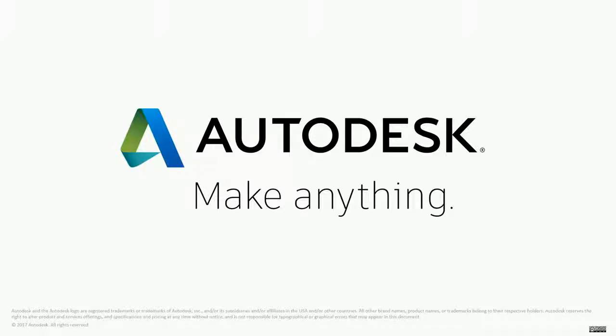With 2017, there was an issue with the country kit. So it was very difficult to go directly using the productivity tool for MicroDrainage. We are waiting imminently, I'm looking at the Autodesk guys because it's due any time now, for the 2018 country kit, and the reason that's on hold at the moment is they're looking to fix that. So with the 18 edition, that link should be fixed, so you should be able to use the direct link between Civils 3D and MicroDrainage itself.